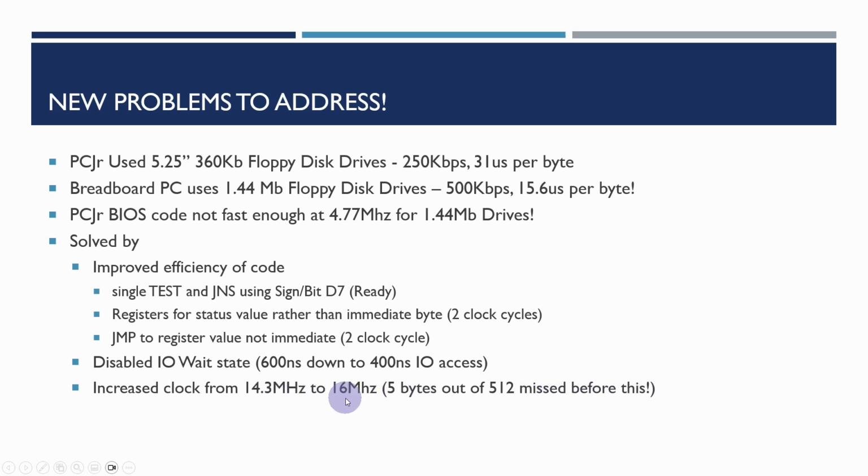data. Now, I think with some of the further optimizations I did, I might possibly be able to switch the crystal back to 14.3 megahertz, but I've been trying to get this working for quite a long time. So for the moment, I'm just keeping it in its working state. So let's take a look at some logic analyzer outputs just to show some of the stages that I've had to go through to fix this.